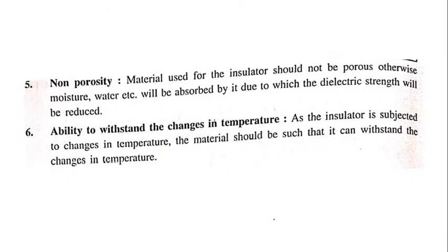Next, non porosity. The material used for the insulator should not be porous, otherwise moisture or water is going to be absorbed by the insulating material and its dielectric strength is going to be reduced. So our material should not absorb moisture or water from the surrounding medium, right? So this is the fifth one.